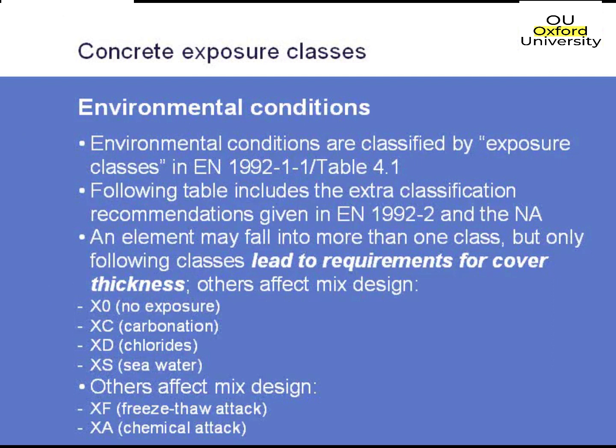Basically you've got the X0 exposure class, which is concrete inside. You've got XC, which is carbonation. XD, which is if you've got icy salts and things like that on your structure or near your structure. XS is your seawater, if you've got something that's sitting in seawater or near seawater. And then you've got the other ones like XF, which is freeze thaw, and your XA, which is your chemical attack. All these are given in Table 4.1, as I said.